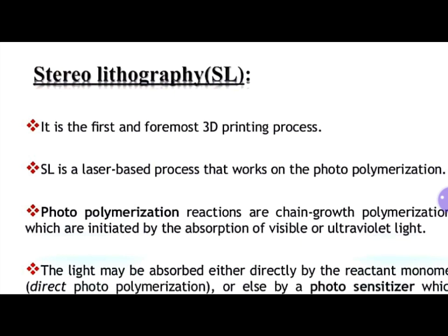So here, as I have said, we are going to use liquid photopolymer resin in order to create the 3D models, and it uses some photostat techniques. Photopolymerization reactions are chain growth polymerization, which are initiated by the absorption of visible or ultraviolet light.